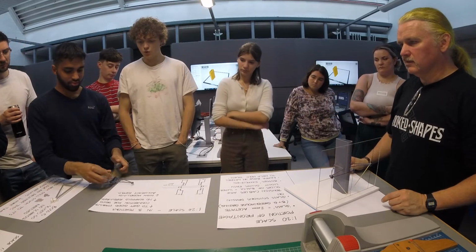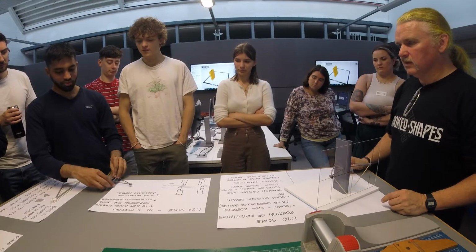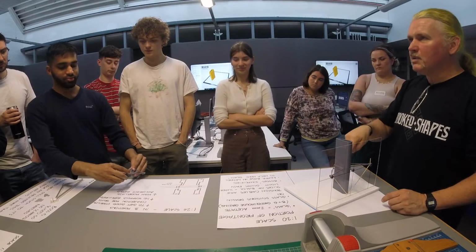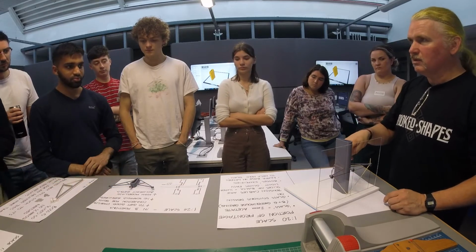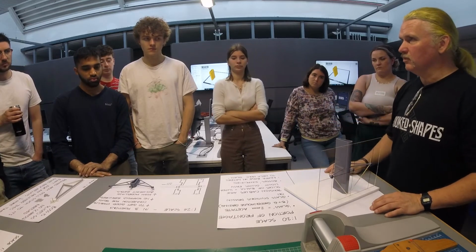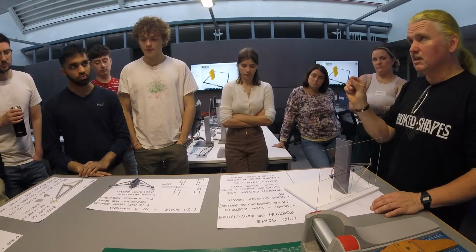so it's just carefully kind of sized. So you notice it's just a little bit flappy. Okay, this was a bit too tight, so that was 0.2mm tolerance. That was 0.3, so 0.25 would have been great. So it's down to that kind of accuracy.